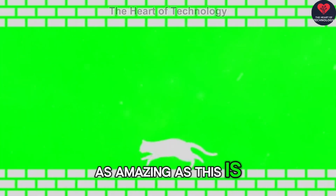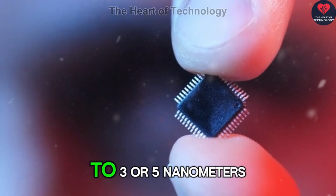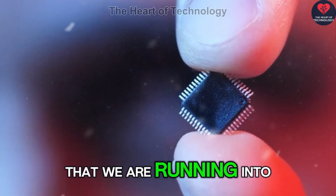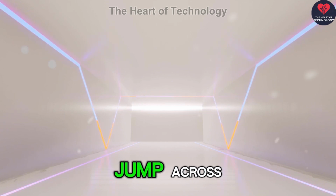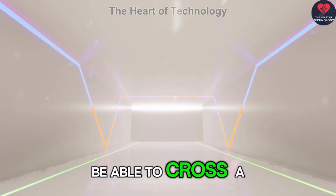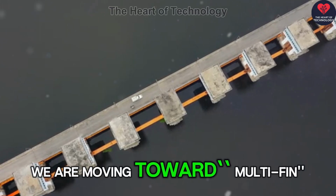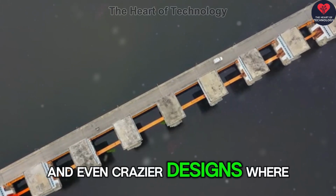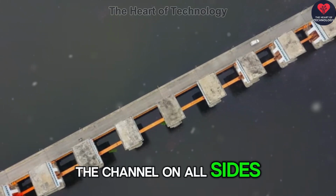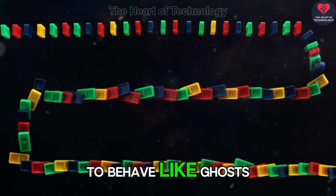As amazing as this is, we are hitting a wall. We have made transistors so small, down to 3 or 5 nanometers, that we are running into the weird world of quantum mechanics. Electrons are starting to jump across barriers they shouldn't be able to cross, a phenomenon called quantum tunneling. We are moving toward multi-fin transistors, FinFETs, and even crazier designs where the gate surrounds the channel on all sides. The Lego pieces are becoming so small that they are starting to behave like ghosts.